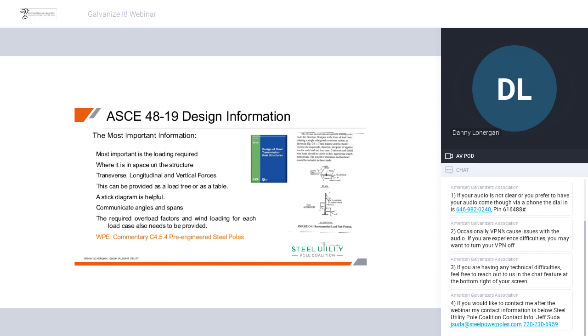But this commentary in the back of 4819 really walks you through some things that a designer and or a selector of a pole, again, a designer, needs to understand. Some of the key topics are the NESC, NESC grade B, grade C. So we're going to touch on that here in a few slides. I mentioned that previously. That's of importance because ultimately the NESC allows a non-wood pole to be designed, if you will, but applied in a different scenario. Loads and capacities.